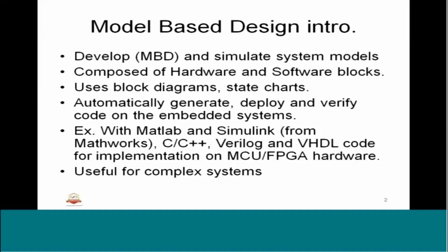those models, with the help of the tool, can be used to generate the code, and that code can be deployed onto the target. Basically, that code can be generated on the host and deployed onto the target, and the target can be verified with the help of target based execution. But before that, we may have to do some tweaking. The auto generated code is not 100% directly usable, so we need to modify it a little.